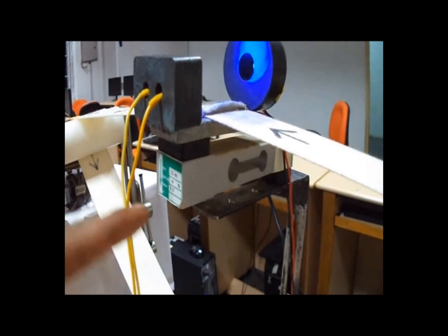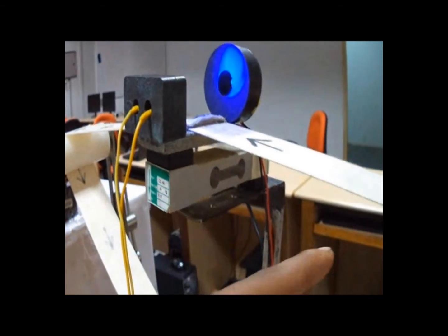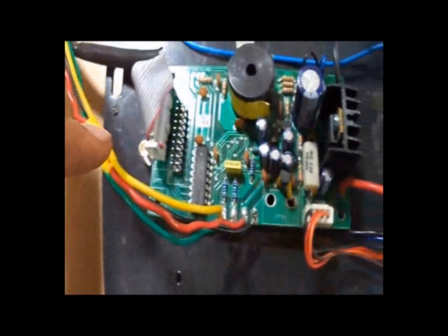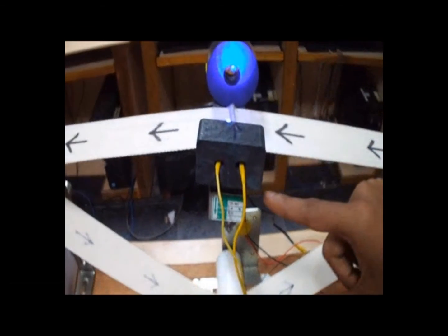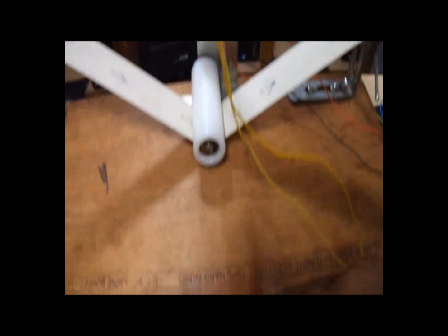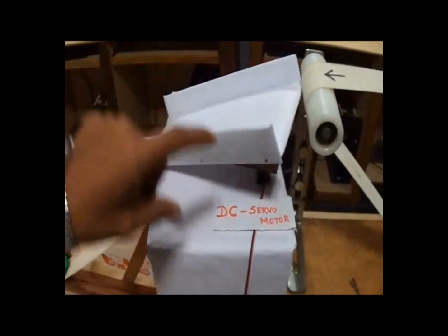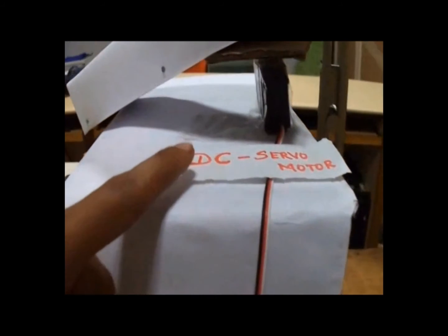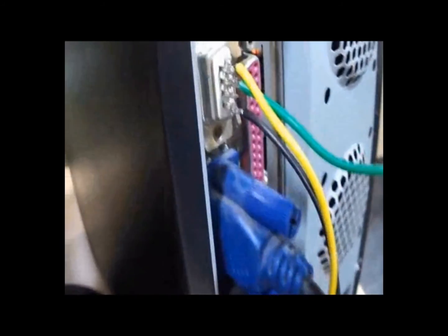Here the weight of the object is measured by using a pressure transducer. This is a CZL601 pressure transducer used to measure the pressure of the object passing over the conveyor. The pressure will be converted into its corresponding weight in the circuit and the data will be transmitted to LabVIEW through the SCB. The measured weight of an object will also be digitally displayed on a 7-segment display for easy analysis. This splitter arrangement is used to split the ingredients based on their weight. This is controlled by a DC servo motor, and the position of the DC servo motor is controlled by the microcontroller circuit. The Atmega 8 microcontroller is programmed to control the circuit. This is interfaced with the PC through the MAX232 IC, and the interfacing is done along with an RS232 cable.